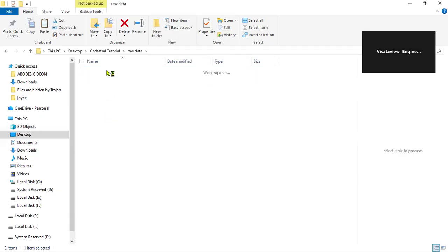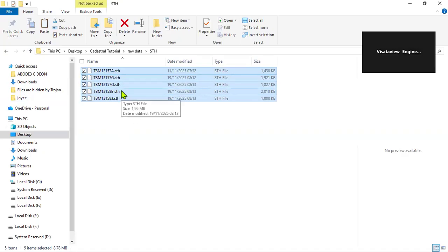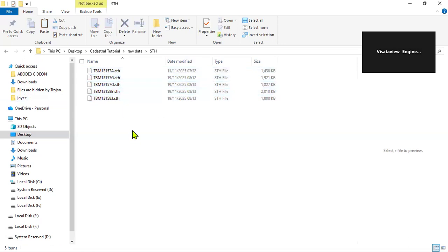Now, this is how your data is. You have to process this one to the Rinex 2.10 that they were talking about before you'll be able to plot it. You have to convert it from this GNSS format to Rinex 2.10, which is the required format you will send to the SMD.